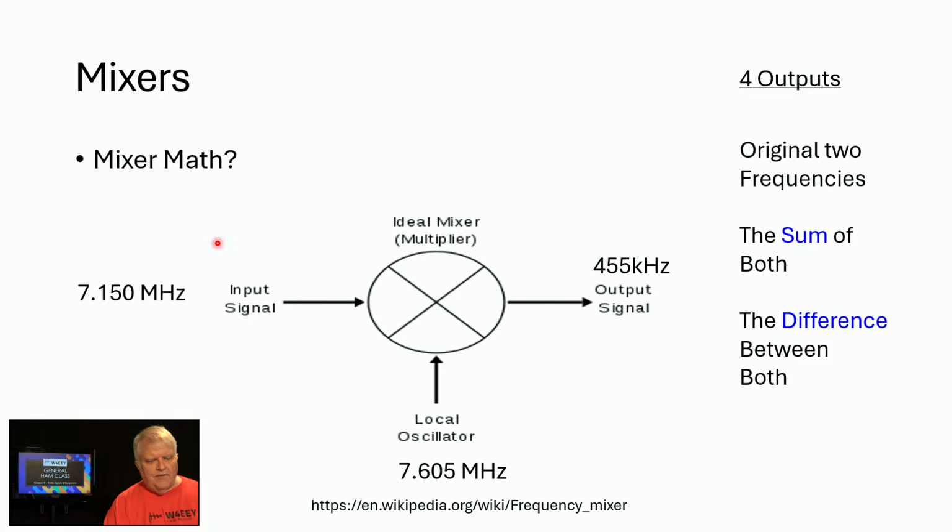So here we have a signal on 7150 megahertz in the 40-meter band, and we have a conventional radio that has an intermediate frequency of 455 kilohertz. And that is a standard. All the American 5-tube radios typically used 455 kilohertz. Many car radios used 455 kilohertz as an IF frequency. A lot of ham equipment, if it was single conversion, Radio Shack's DX150 or 160, used 455 kilohertz as an intermediate frequency where they could amplify the signal and filter the signal for bandwidth.